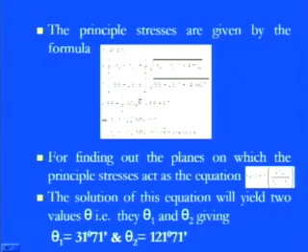The meaning is that you can calculate those things pretty simply once you know the values of sigma x, sigma y and tau xy, plus the sign convention, that is, how the forces are acting and what types of stresses are induced due to these forces: tensile nature, compressive nature, shear stress, and then the complementary shear stress, whether it is tending towards the clockwise or counterclockwise direction.